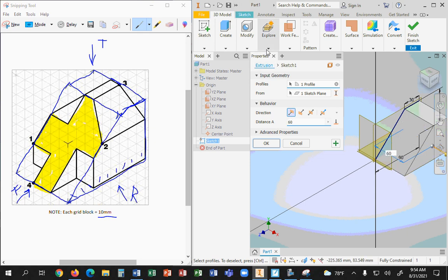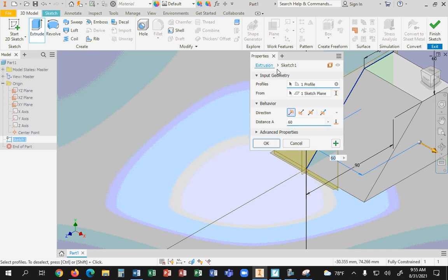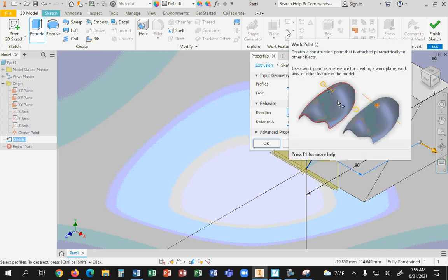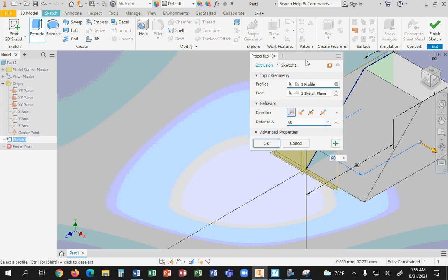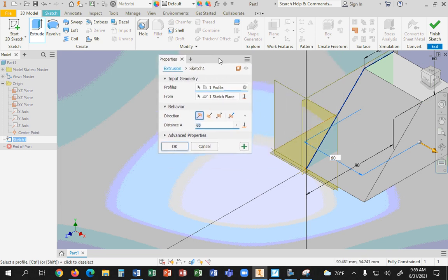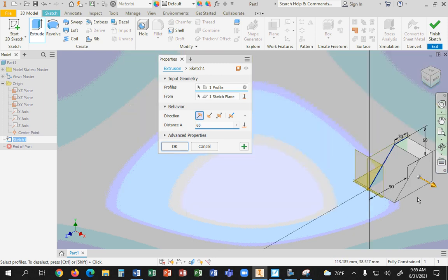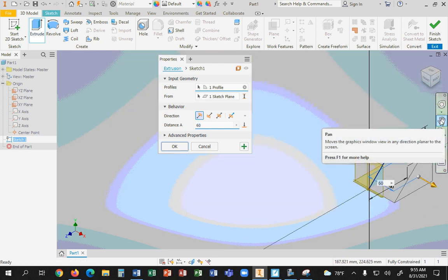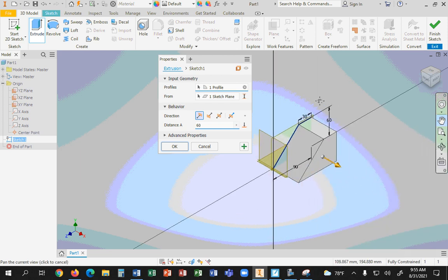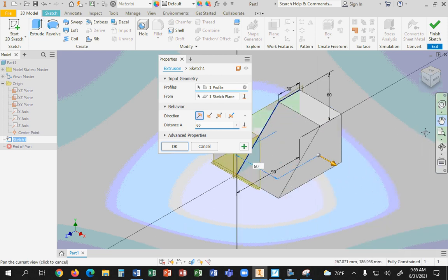Now here's what's interesting to know. Unlike SolidWorks that compartmentalizes extrude cut from extrude, Inventor does not. Everything is all encompassing. Obviously, it's the first object, so there isn't much else you're going to do to it. By the way, when you want to pan, pick the little pan option so you can pan over, or it's how you zoom. Got it?